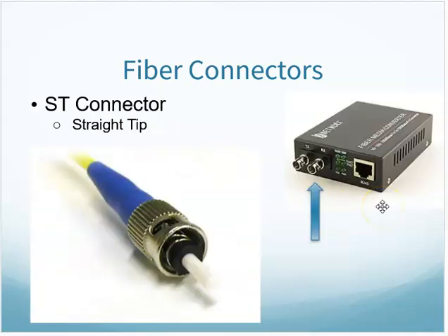Here's each one up, again close and personal. Here's the ST, straight tip, and then the port it would clip on, connect onto. And this just twist locked on. This was actually a very solid connection. The fiber line was really good. The light transfer from the fiber to the device was really good. So quality connection used for quite a while, but there were polarity issues. You could easily hook that up wrong, on the wrong side, if you will.